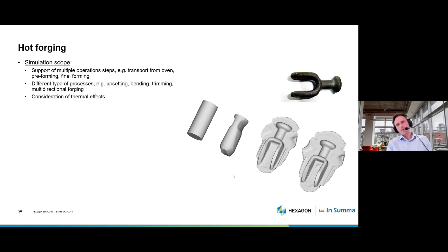If you think about the solver behind this simulation technology, it is quite sophisticated, because what you have in terms of the material flow, maybe in this flange area, you can see a lot of material which is either splitting or overlapping. So the solver which is used to simulate hot forging type of processes is quite robust, and you can have all sorts of overfolds or material folding onto itself easily simulated without any kind of numerical issues, and you have a good estimate what happens with the flow of the material at any station of the process.